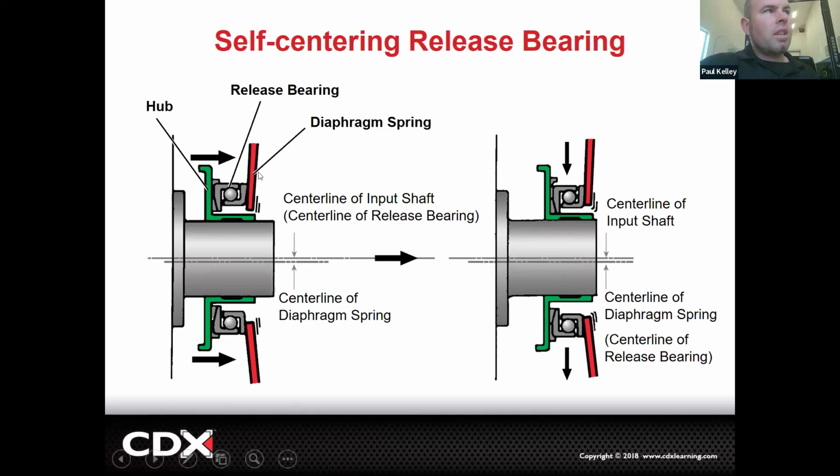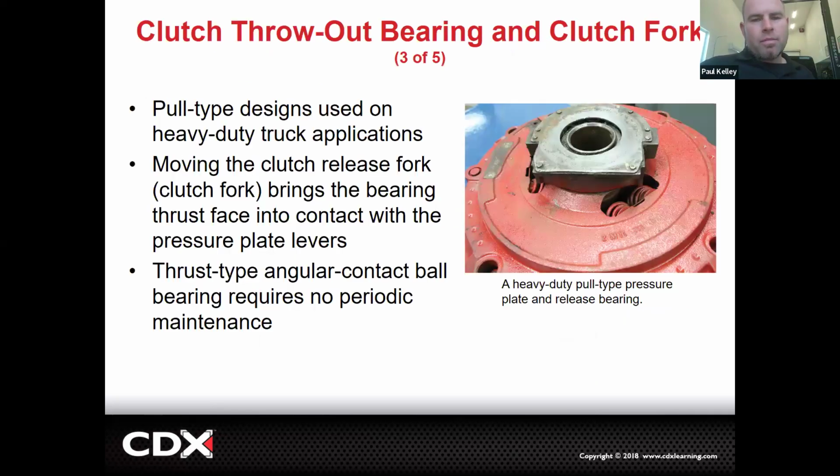Because you can see this bearing is what allows this to stay still while this spins. And then, of course, when you actually have them engaged, they should both be spinning. But when they're disengaged, one's going to spin, one's not going to spin. So it's all changing the load on that bearing. That's how we diagnose it.